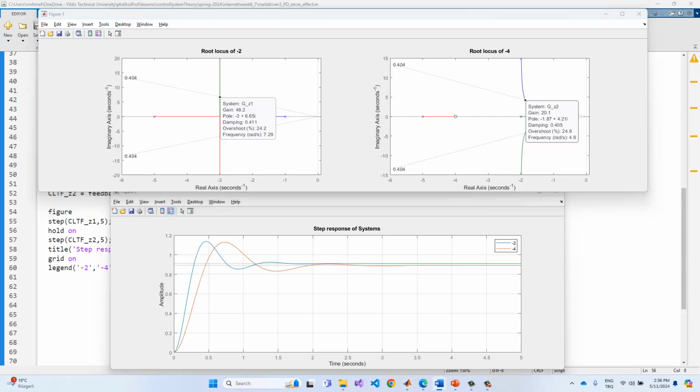Okay. And so we can easily analyze the system based on this information, but just remember that if we select another response or another time variable in here, for example, if we update the overshoot value up to 10 or 50 or 5, then we need to select a new gain for this system in order to create the proper values of the closed loop transient response.